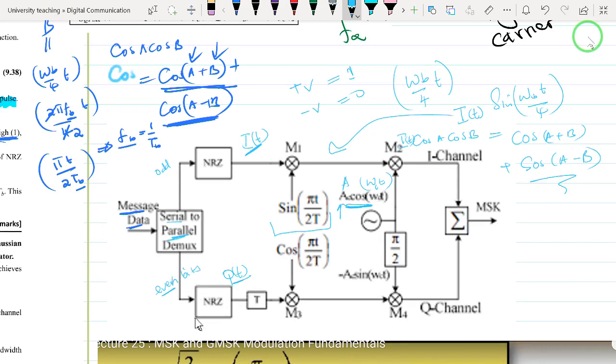They are taken through the NRZ encoder to give us positive going pulses for symbol 1 and negative going pulses for symbol 0. Then they are delayed by a delay function, and therefore we are able to obtain Q(t−T_b). Therefore the signal will be lagging by 1 bit duration.